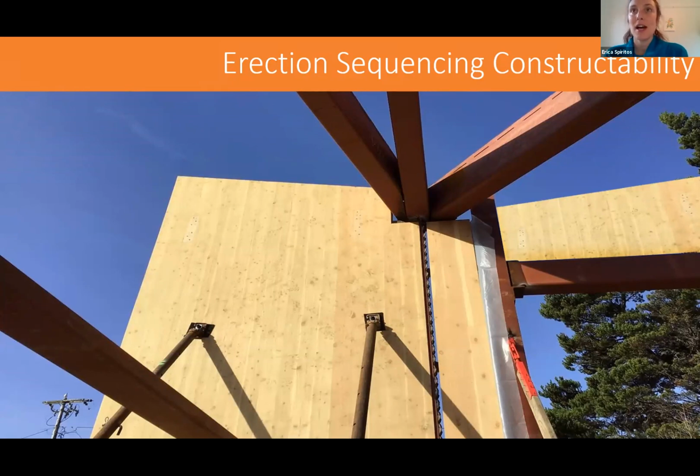Yeah, so actually this just brings me to one other point, which is that project delivery method really matters for mass timber. This project was a public job, design, bid, build. We had no insight into the design process or no opportunity to provide feedback. And so we find that mass timber projects tend to be really most successful when there can be constructability feedback incorporated into that design process. So we typically advocate for CMGC or design build, or at least design assist approaches to delivering mass timber buildings.